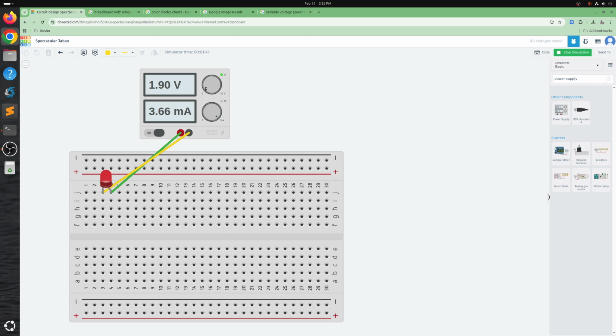So again, if you buy these diodes in real time, you will get to know the exact input value from the manufacturer's chart. It might vary from manufacturer to manufacturer. So here it seems the threshold value is at 1.9 because if I decrease it slightly below 1.9, even if I keep it at, let's say, 1.7 or 1.8, it's not blinking, but at 1.9 it's blinking.